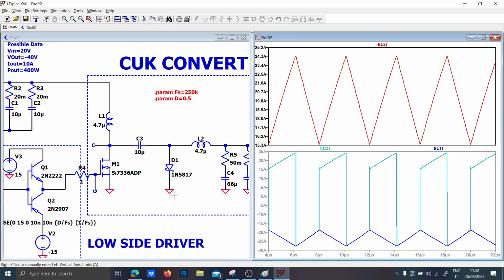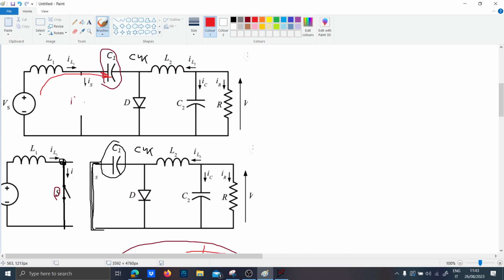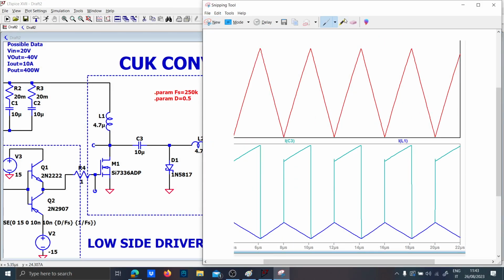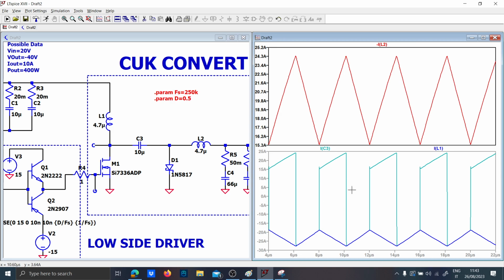So in the first time, as I said before, the current is given by the inductor L1, and so you will have this current here, this straight here. Let me annotate it for you. As you can see, you have first this, which is the current of inductor L1, and then you're going to have this one, which is the negative current of L2, which should be going like this theoretically. And that's the reason why you see a current like this.